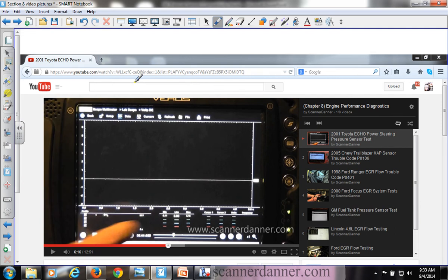What do we have? 0, that's my sensor ground. One of the two 0 readings was the sensor ground. I'm not sure which one. How's my ground? Good. Do we need to check the ground? No. Why? Because signal was also 0. So we're left with what? Either a short to ground in the signal wire, or an open in the signal wire, or a bad sensor.